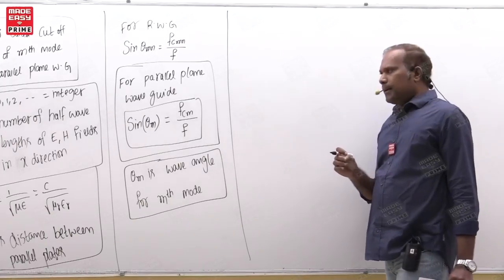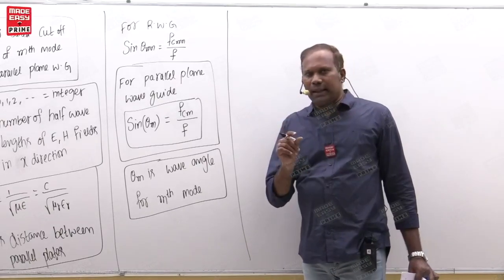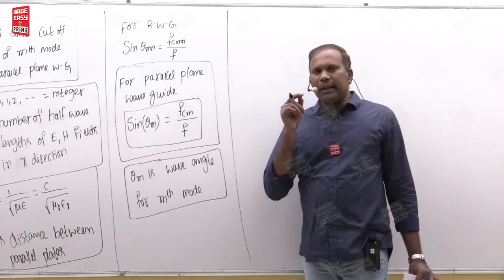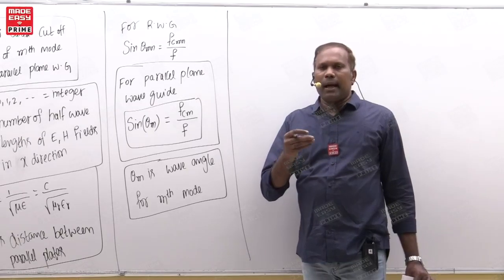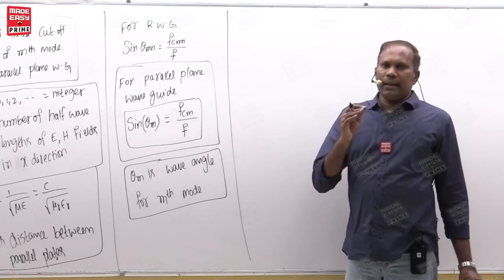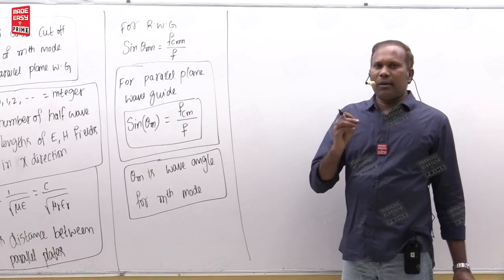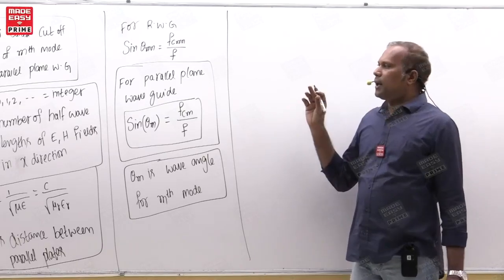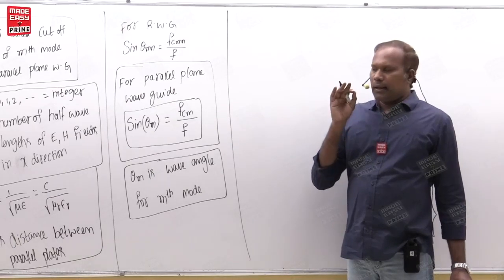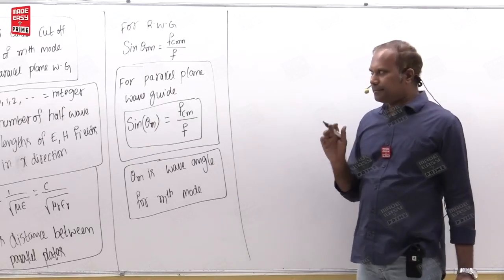Similarly, here also you have a resonant circuit. In the network theory, LC components are available in such a way that resonant frequency is in hundreds of kilohertz. Now, that LC resonant circuit works for hundreds of kilohertz, but that won't work for gigahertz frequencies. For gigahertz frequencies, LC value should be very small, so that is not possible to design.